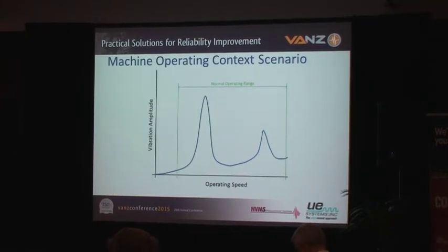And we all know we like to avoid running on the critical speed during normal operation, but because it's a variable speed, variable load machine, it could run anywhere within that speed range. And generally speaking, if I remember correctly, normal operation was really something like from 1,700 through 5,200 RPM. But in that range, what I've identified as a normal operating range, there are two critical speeds.